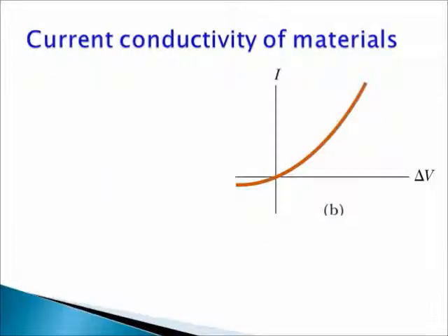Whenever you get an electric element and wish to explore its electric properties, you can perform a very simple yet informative measurement. Connect a potential difference delta V to the terminals of the element and measure the current that goes through the element. Plot the dependence of I versus delta V for several values of delta V. The typical dependence that you will observe is shown in the graph. The larger delta V is, the stronger current you will observe.